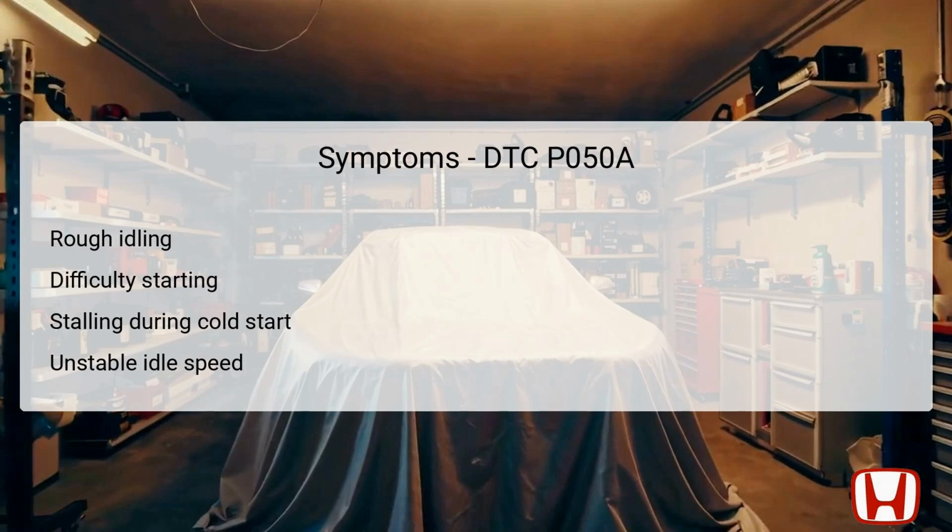Symptoms associated with DTC P050A primarily manifest during cold starts. Drivers may experience rough idling, characterized by an uneven or fluctuating engine speed. During initial startup attempts, the vehicle may also exhibit difficulty, where the engine hesitates or fails to start altogether.